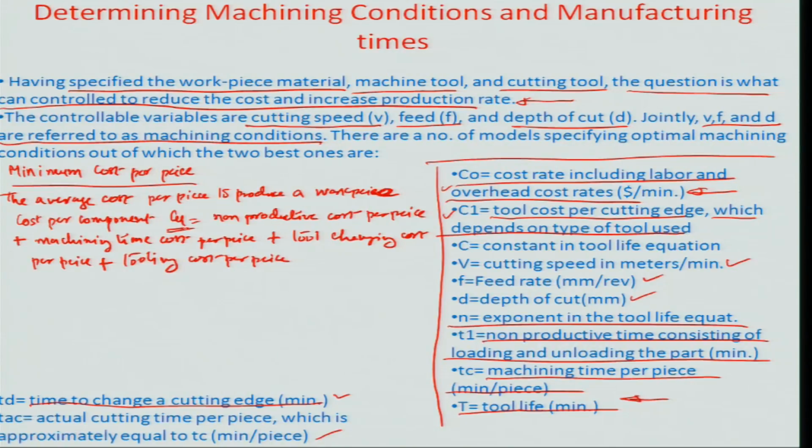And if I really look at some of these parameters that I have illustrated on the right here and some in the lower portion of the slide, we can first do something about the tool life, so that we have an idea of how frequently we need the tool changing. So obviously the tool life equation is a standard format of the Taylor equation, VT to the power n equal to C, which is the constant, and n of course is the index which we are talking about in this particular case. So the overall cost per piece then would be in terms of the